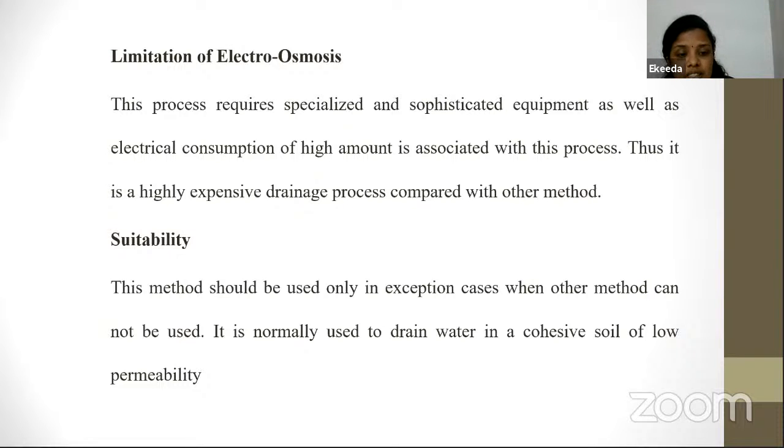Then suitability. This method should be used only in exceptional cases when other methods cannot be used. It is normally used to drain water in a cohesive soil of low permeability. So to increase the permeability of a particular soil, we can use this method.